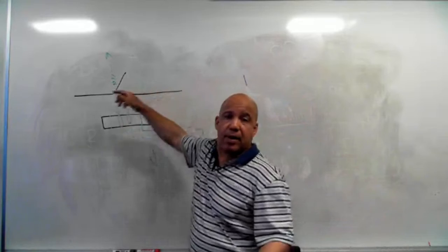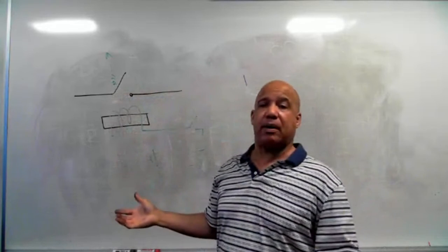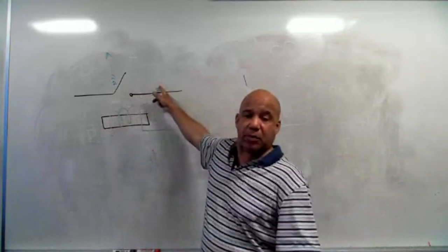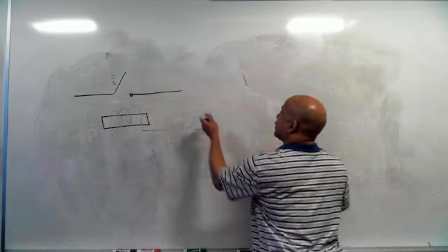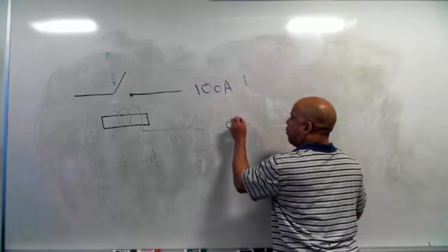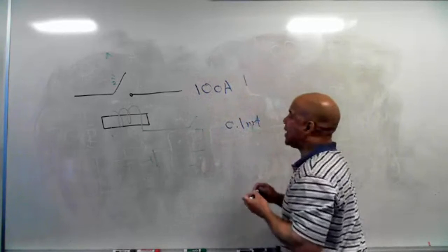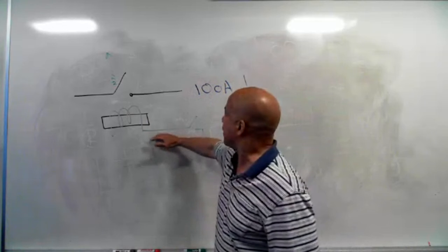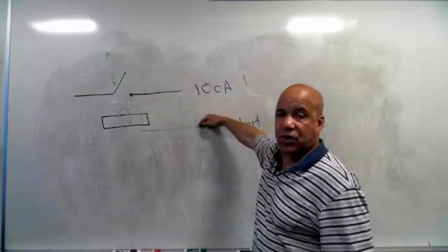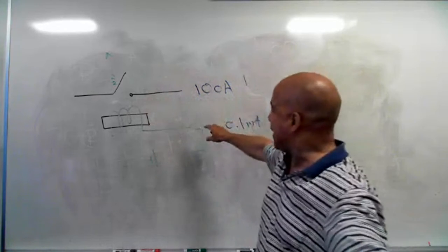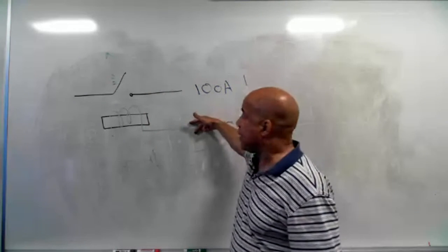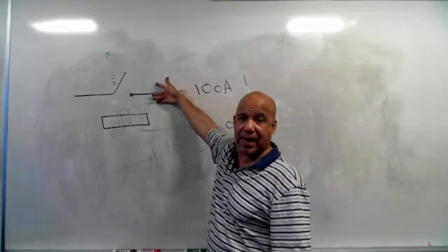This circuit here, that switch can be as big as I want it to be. So I can have this switch and wire so heavy that it might control 100 amps. Maybe I have 100 amps of current here in this circuit, and maybe 0.1 milliamps in this circuit. So I'm using a low current circuit to control a high current circuit. You still got to close the switch though, but I don't have to physically be there. I can connect this to a computer or some device so when I get current here, I can have this switch open or close automatically.